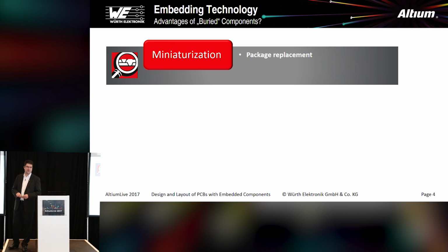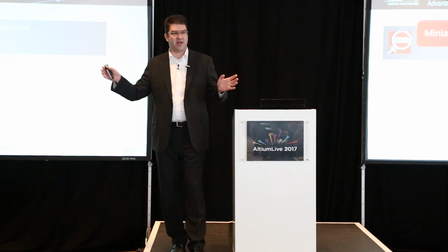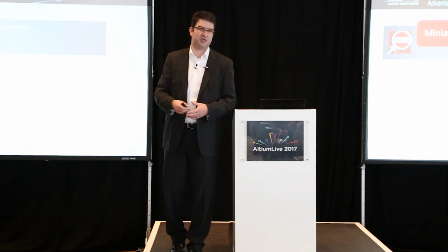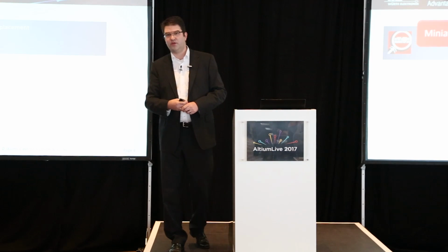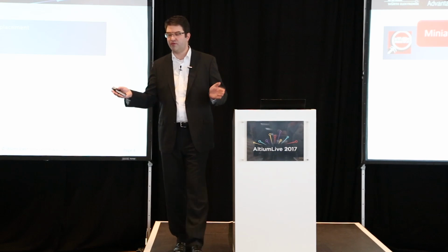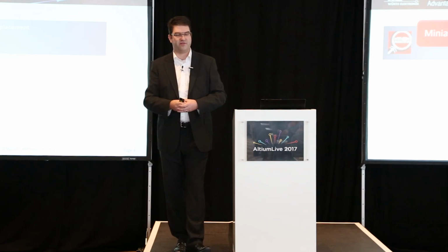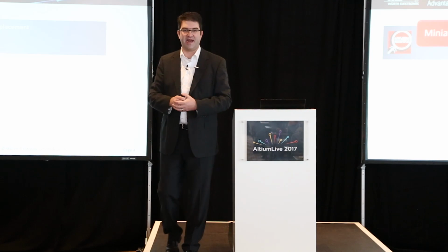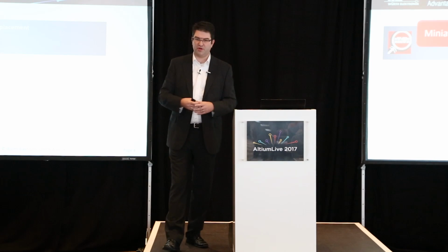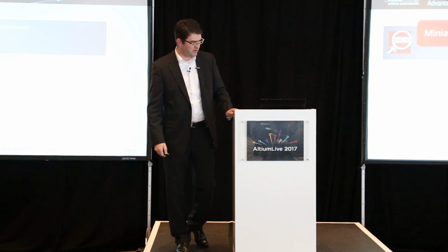Why would you do that? Well, actually, we are working on a big panel. A standard panel is 18 by 24 inch. So you get a lot of components being done in parallel compared to a lead frame technology, for example. In addition to that, we can still rely on those standard PCB technologies, which means you can make through holes, for example. So you can have a package with connections on the bottom side, and on the top side you can add pads for the next set of components. So you can make real systems in packages very easily with that kind of technology. So that's one part of it.